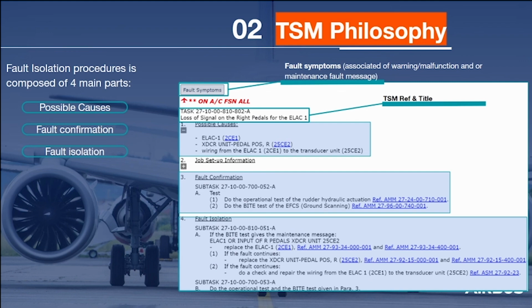It provides the most efficient troubleshooting following several criteria defined within our design office, such as the probability of the failure, the time of check, the cost, and it also defines all the tests that can be used for the isolation. An isolation test can be, for example, a visual check, a power supply check, etc.